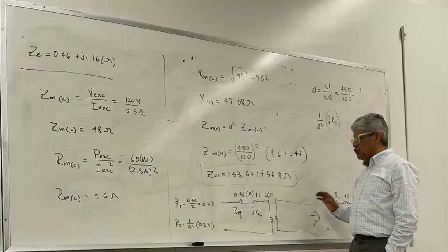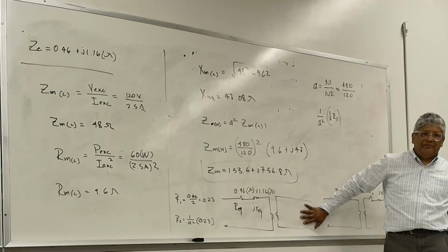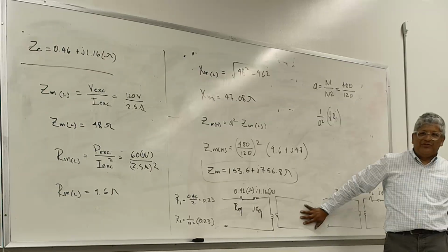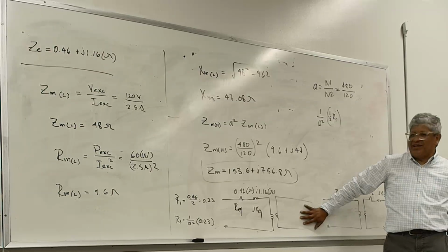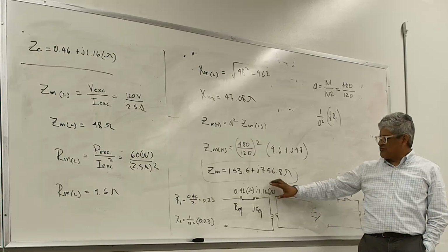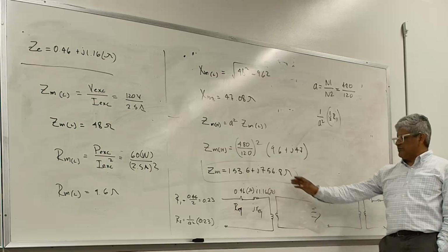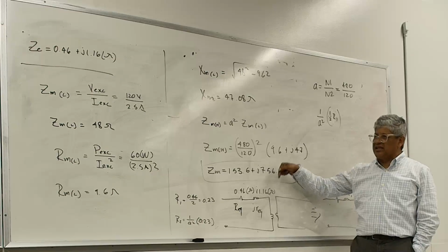Because usually when you energize the transformer, there's no load, so it's an open circuit. That's when the excitation branch comes into play. As a matter of fact, the way this magnetizing branch performs is what we call the excitation current.